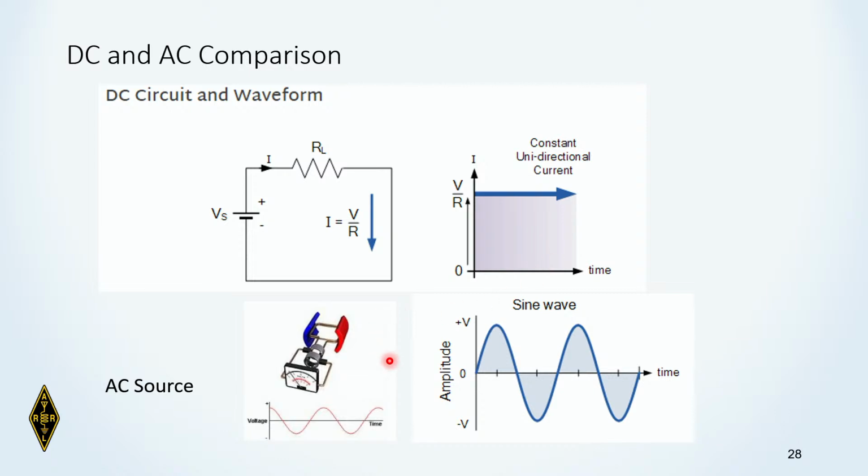With AC, that's operating a little bit different. One of our past students described this as electrons sloshing around, which I thought was a pretty good description. What happens is the voltage starts at 0, increases up to a peak value, and then decreases to 0, negative, back to 0. So here's a little picture of a generator. I'll have a larger version of that coming up. But sine waves are just every place in nature, and more on that as we go along.